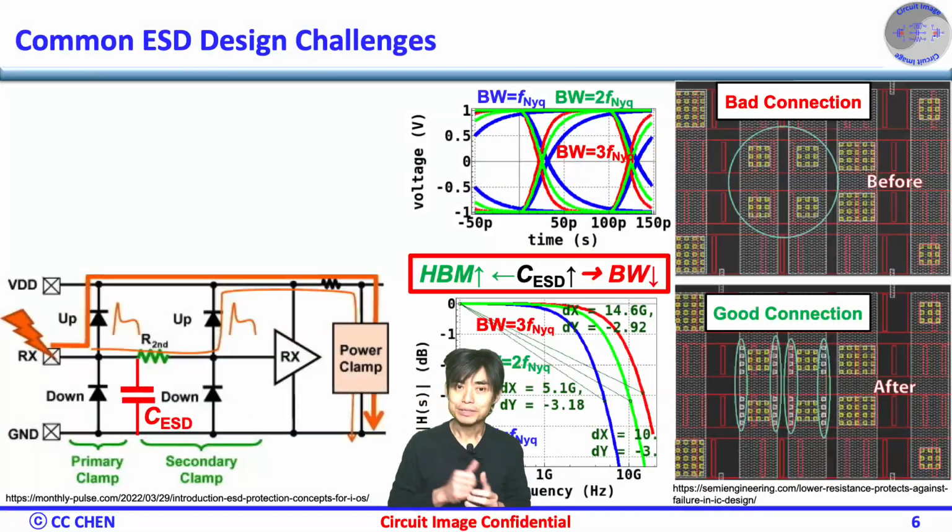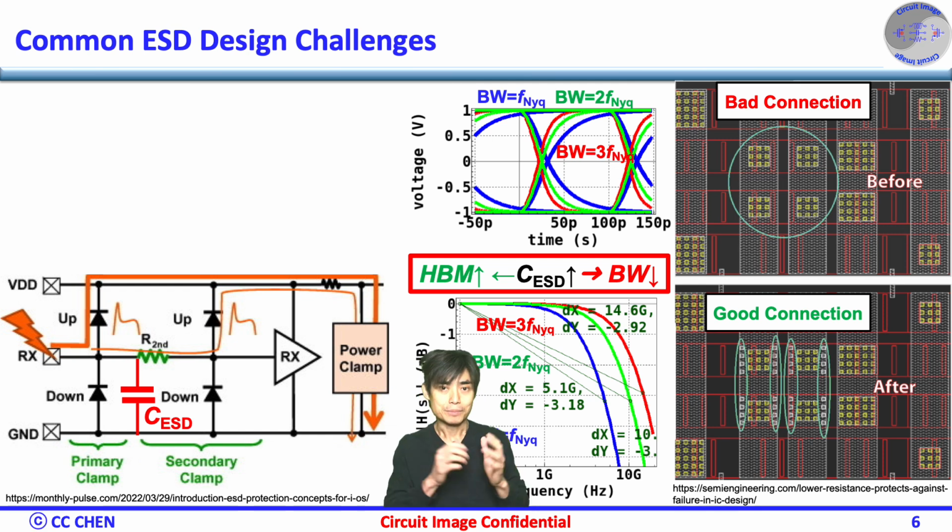Designing for ESD protection comes with challenges. One major issue is balancing protection and performance. High-speed circuits are particularly sensitive to additional capacitance from ESD structures. If protection elements are too aggressive, they can degrade signal integrity. Conversely, weak protection leaves the circuit vulnerable to damage. Finding the right trade-off is critical.